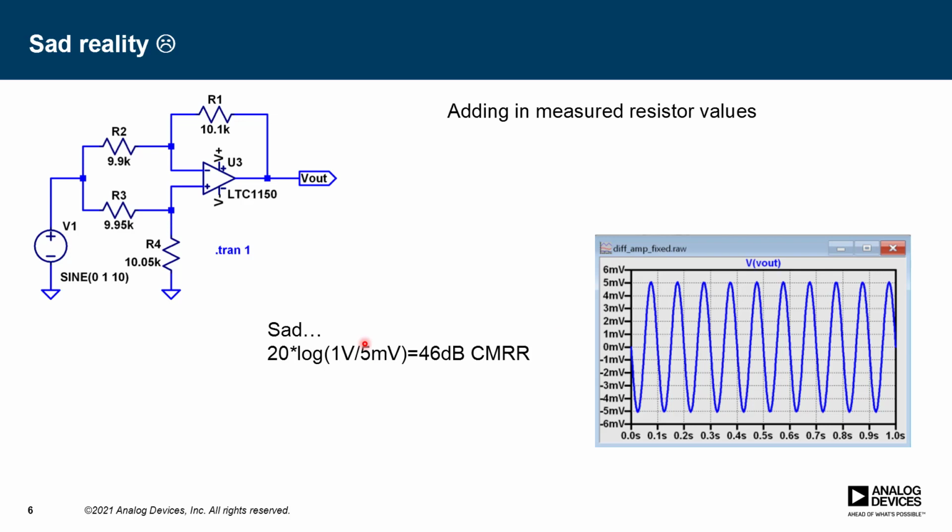So if you take the student who's got a frustratingly low performance circuit, send them to the most expensive meter that you have in your university lab there to measure these resistors. So get a real measurement of what these values are, plug them into LTspice, and see if you can perfectly model this imperfection. So if you're seeing a wiggle of plus minus 5 millivolts on the bench, do we also see this in simulation? Now you're starting to build intuition about your circuit. It didn't work, you figured out why it didn't work, and now you can simulate it with this theoretically perfect simulation of an imperfect circuit.